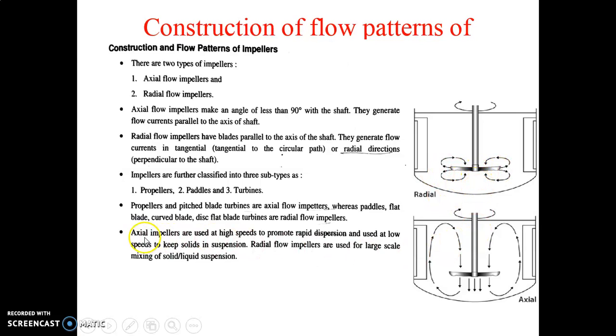Generally the axial flow impellers are used at high speed, and they are also used at low speed with solids in suspension. That means if you want to mix solid plus liquid, at that time you have to keep the speed of the impeller slow.